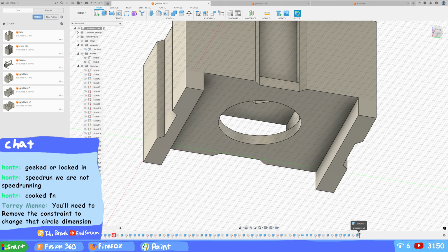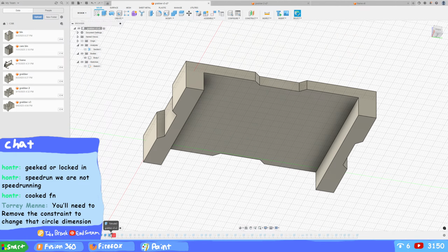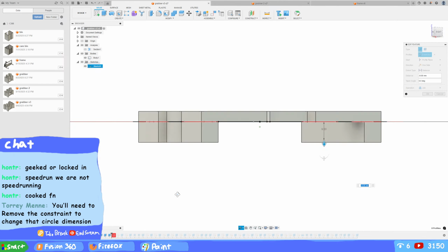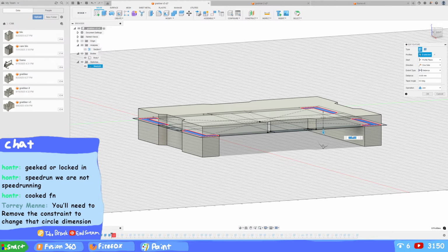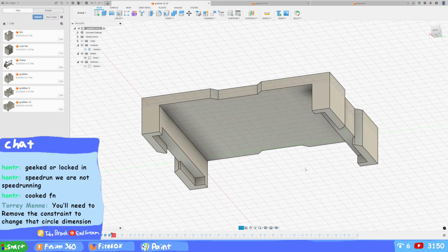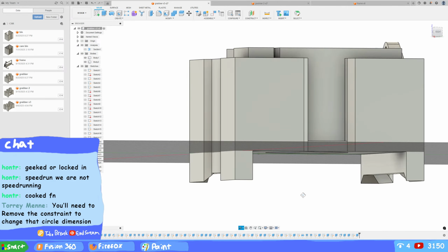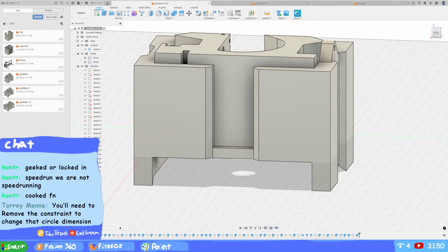Okay, let's go back in time and see what this extrude was for. Oh, okay, this one needs to go down -9 plus -5. There we go. And then the chamfer should work. Perfect, okay, great. Wow, incredible, isn't it?